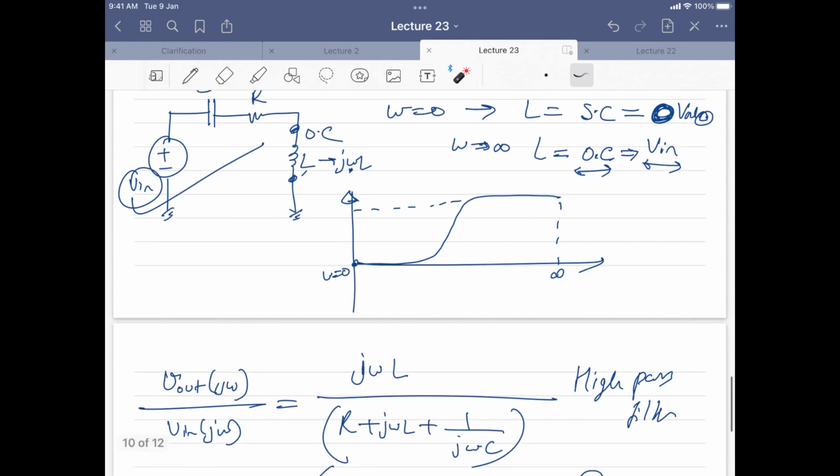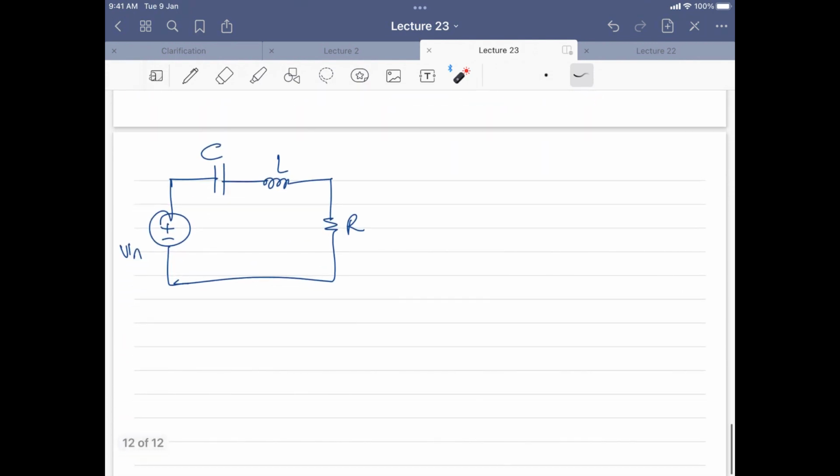Okay. So in the band pass filter, we cannot analyze whether it's a band pass filter or not intuitively, because you can see R will remain there even when omega is 0 or omega is infinity. So we do not know how to analyze it for band pass. In this case there is no other option than solving for the transfer function.